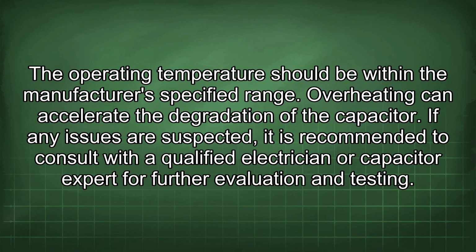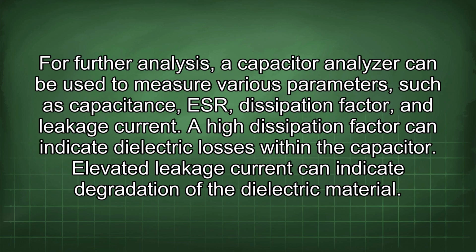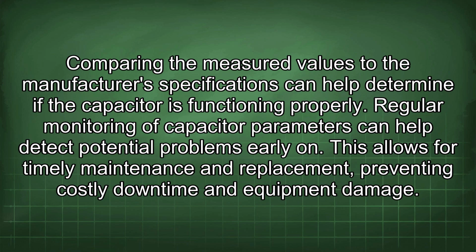and testing. For further analysis, a capacitor analyzer can be used to measure various parameters, such as capacitance, ESR, dissipation factor, and leakage current. A high dissipation factor can indicate dielectric losses within the capacitor. Elevated leakage current can indicate degradation of the dielectric material. Comparing the measured values to the manufacturer's specifications can help determine if the capacitor is functioning properly. Regular monitoring of capacitor parameters can help detect potential problems early on.